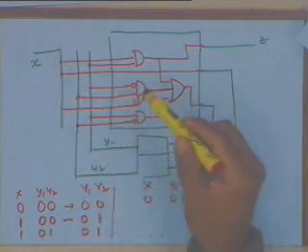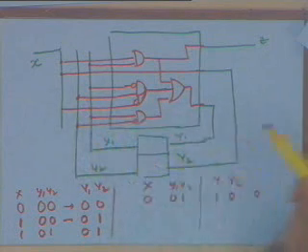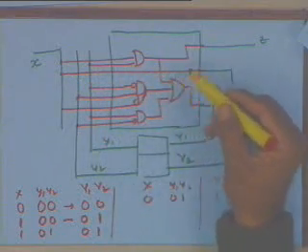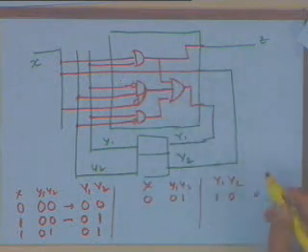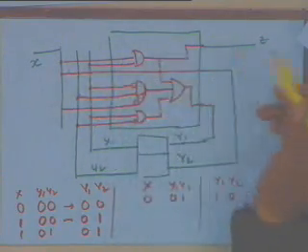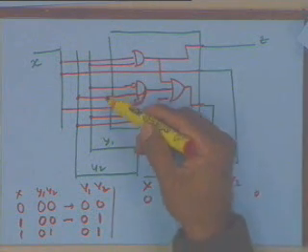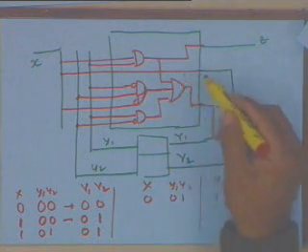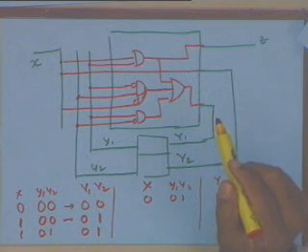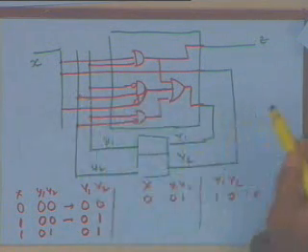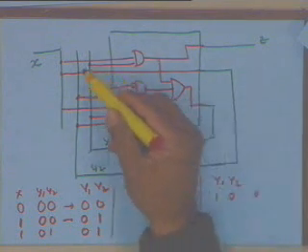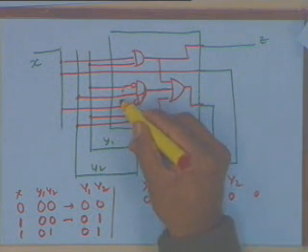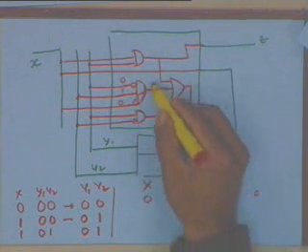Now as soon as this x becomes 0, the problem that comes is when x becomes 0, if immediately my y2 also becomes 0, x is 0. Of course output I have no problem, output will remain 0 because x goes from 1 to 0, y1 was 0. But now how can the y1 become 1? Because I need y1 to become 1. y1 can become 1, there is a path actually for y1 to become 1. If y2 was 1 before and you sense x going to 0, so y2 1, x 0 and y1 0 will make this actually 1.